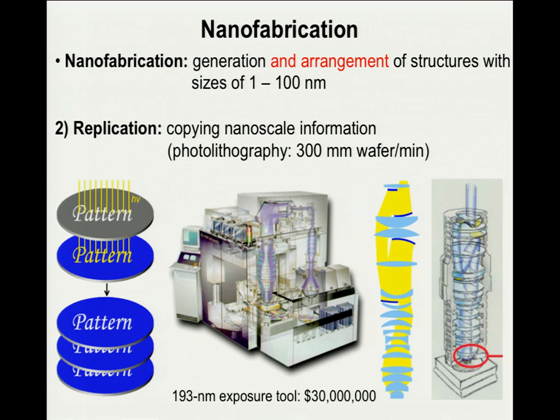So most of the cost is actually embodied in the precision with which these mirrors and lenses need to be positioned in the device in order to scale down the image and get it to impinge exactly where you want it on a wafer. Because a microprocessor, so the Intel Core M or whatever, has up to 50 layers of photolithography that all have to be very precisely registered.